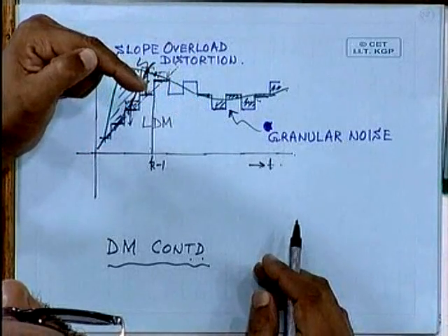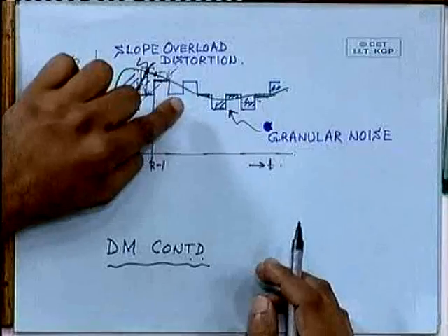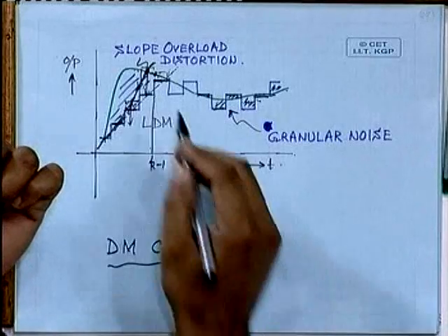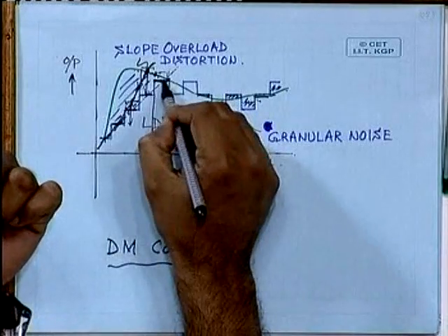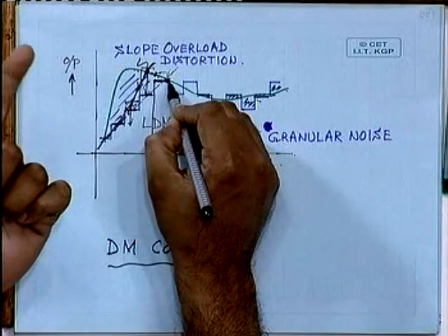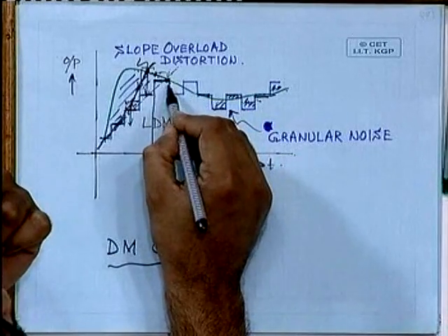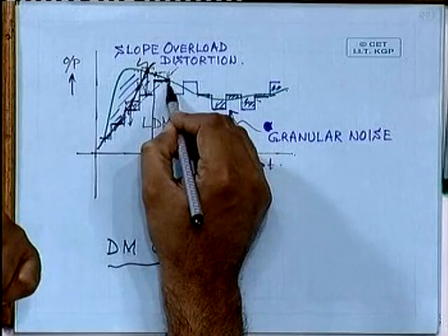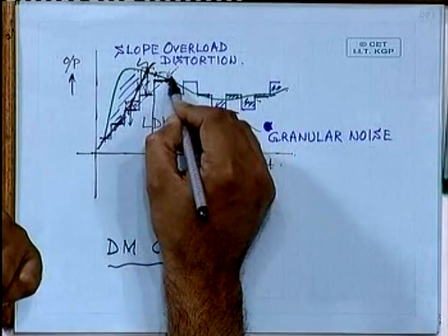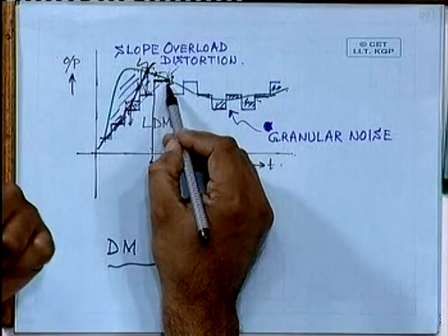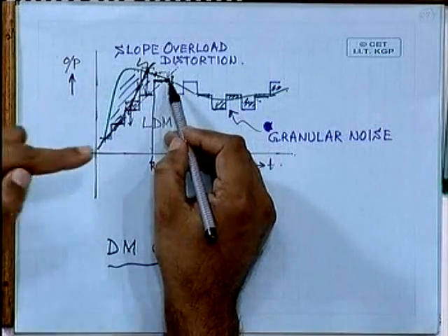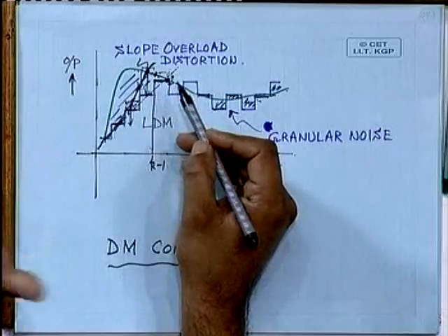So, what is necessary is a changeover, that the polarity of the quantizer changes from what it has been recently, which happened here at this instant. At this instant, the signal amplitude was a bit less compared to the quantizer output. How much difference was there between the actual signal value and the staircase approximation from the delay unit? Very small. What I am talking about is the maximum difference that is allowed for this changeover in polarity to occur, and that maximum difference is not 2s but s.